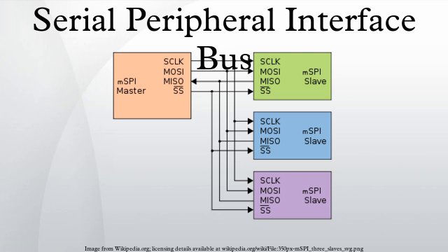The whole chain acts as an SPI communication shift register. Daisy chaining is often done with shift registers to provide a bank of inputs or outputs through SPI. Such a feature only requires a single SS line from the master, rather than a separate SS line for each slave. Applications that require a daisy chain configuration include SGPIO and JTAG.